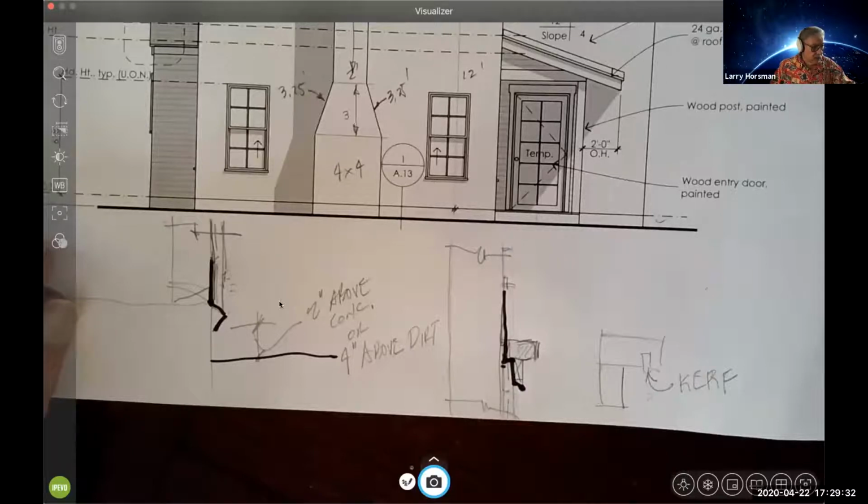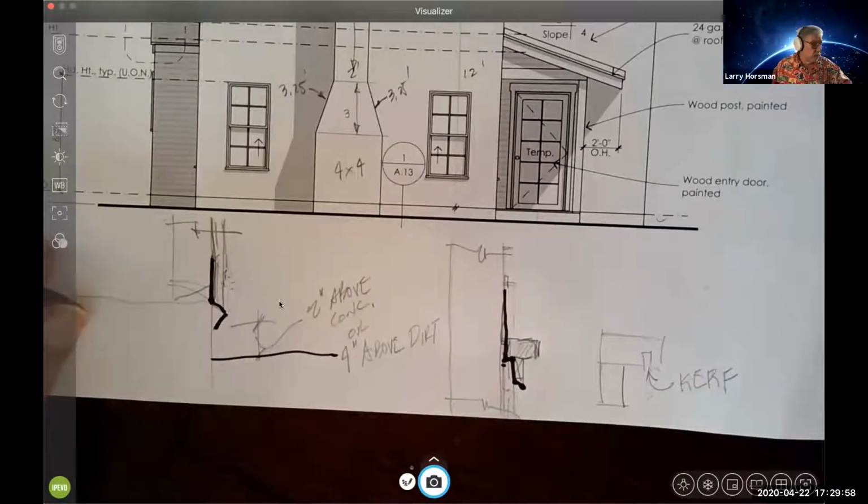So standard is a 3-coat. You put a scratch coat, a brown coat, and then there's a finish coat. So scratch coat goes on first. It's the thickest. That can be either machine applied where they spray it on, or it can be troweled on by hand. And then they come back before it hardens, and they actually rake it with a bunch of little wire fingers. So that provides the interlock or the base for the brown and finish coat.